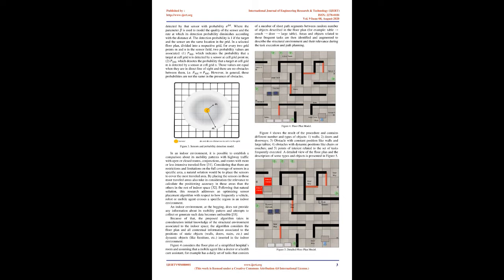On the other hand, because sensor measurement is unavoidably affected by ambient noise, methods that take uncertainties into account become practically applicable. One potential method in this category, the so-called information entropy, is widely adopted to address measurement uncertainty by finding the best match of structural testing that can minimize the negative consequence of uncertainty [19,20,21]. The process of sensor placement search and determination can be mathematically formulated as an optimization problem in which discrete variables represent the available sensor positions in the structured system. The objective function, to be minimized or maximized, is defined to measure the performance of a sensor configuration.